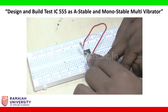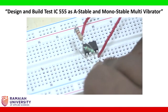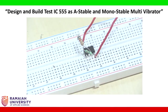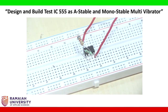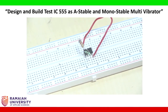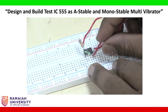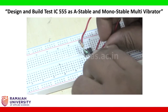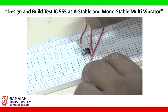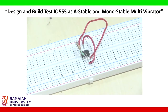See here, I connected a 3.6 kilo ohm resistor in between pin number 6 and pin number 7. Now I want to make pin number 6 and pin number 2 a short. This is pin number 6 and pin number 2, and I made it a short.